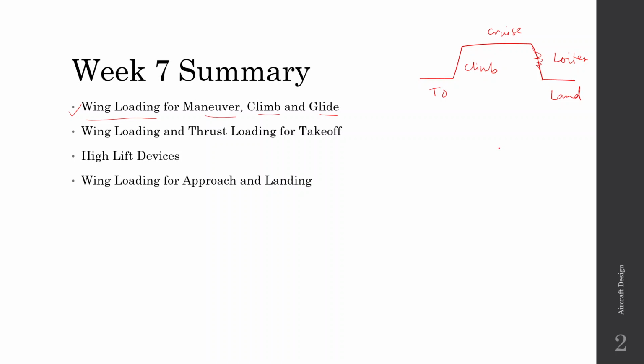For each of these phases of flight, we have to use the fundamental equations to find thrust loading and wing loading. Then we have to see which phase we have to give priority to, and according to that, we have to select values for this.